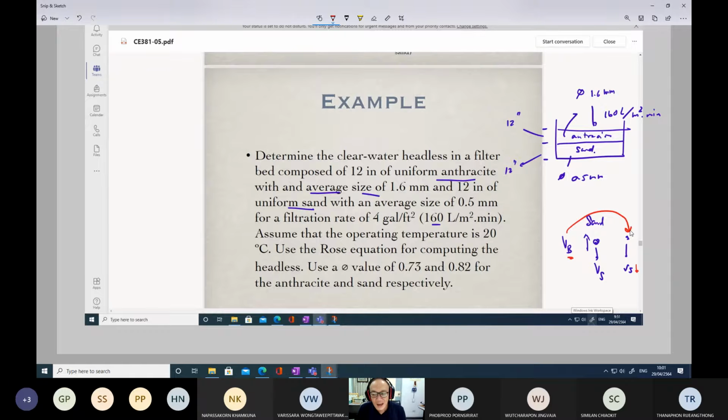So if we apply a low backwashing rate, the sand layer will not be cleaned efficiently. In this case, we may need to blow air so that the air will help to increase mixing and abrasion so that all the dirt stuck in the pores will be washed out.